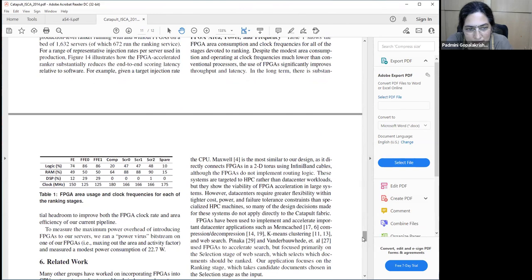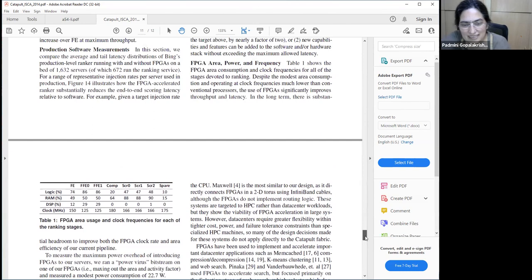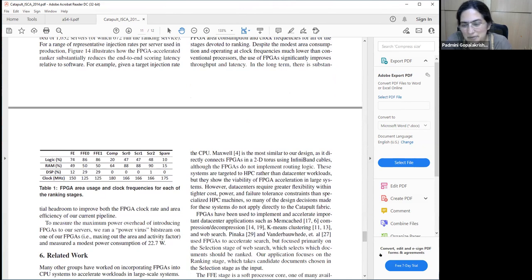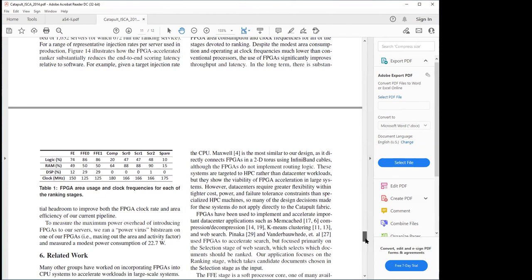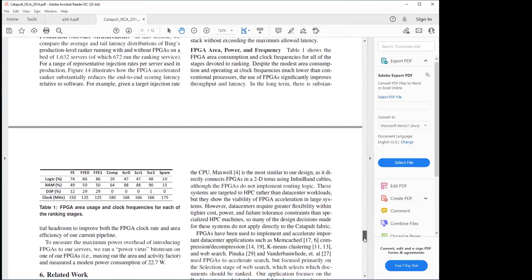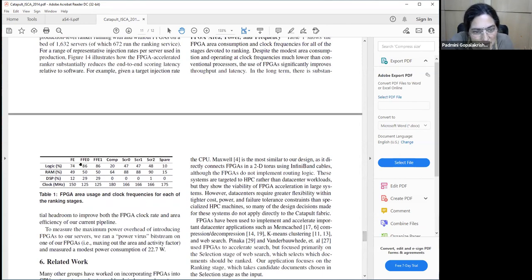So in this, if you see, right, or is this because it's a very old work? One reason could be that it's old work, and they themselves say there is substantial headroom to improve. So this must be a preliminary implementation is my guess. Okay. But the minute you start hitting, we definitely see this, logic utilizations of 70 to 80%, timing closure becomes more challenging because you need space to route everything. And you can see that those are the blocks which tend to run at lower frequencies, right?